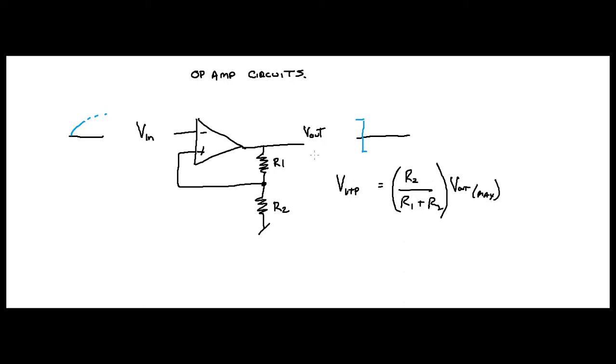So now what's your new voltage? You're going to have a lower trigger point, aren't you? That's going to be the same, except your V out is going to be negative, isn't it? So it's going to be a negative voltage. So you could have multiple transitions up here, right? It's close to where it's transitioning, but it's already made the transition, and this voltage has changed. So now you aren't going to have that switch bounce, all right? Because it's not comparing it to the same value once it makes that initial transition.